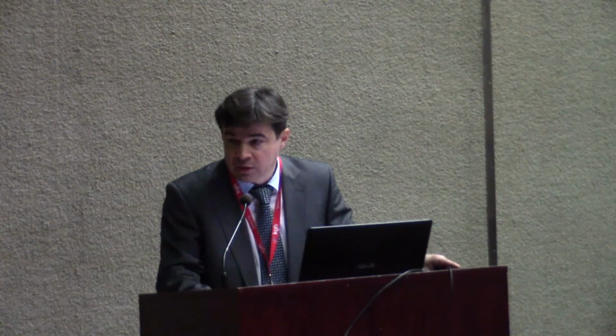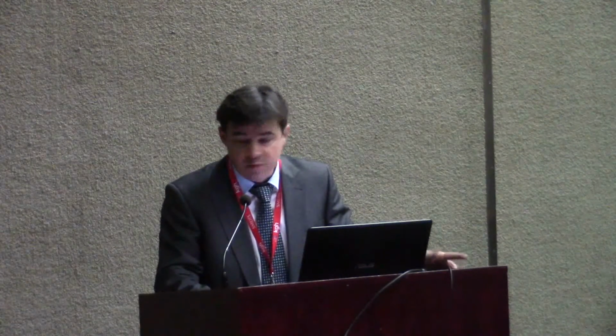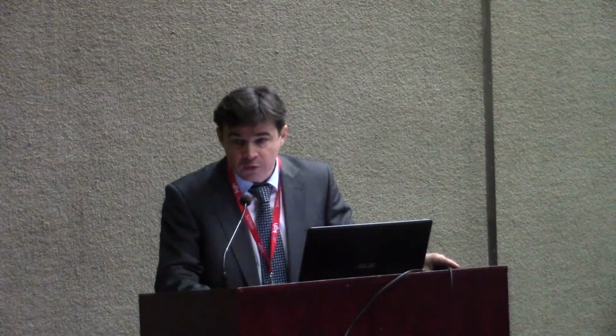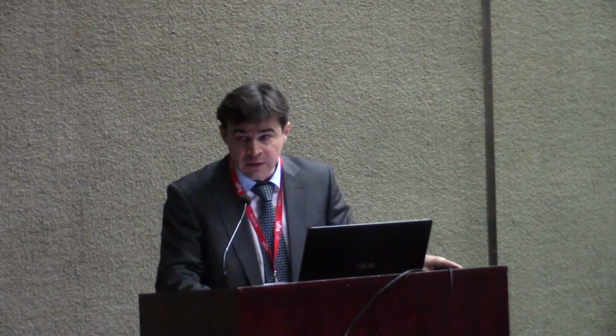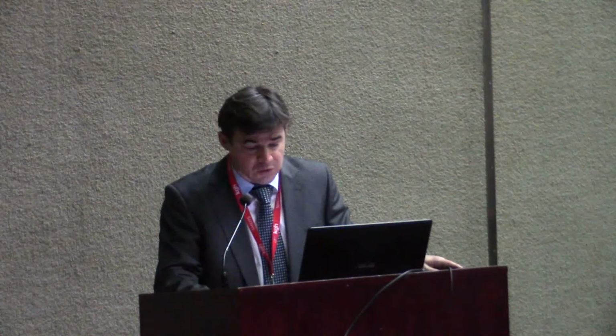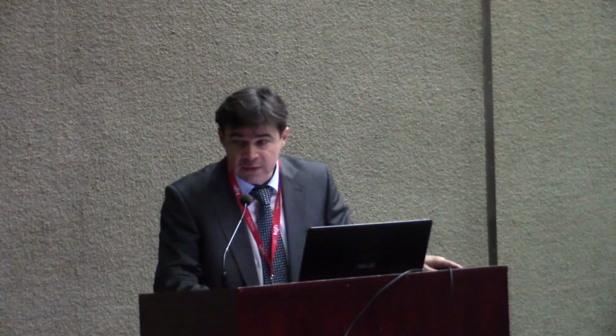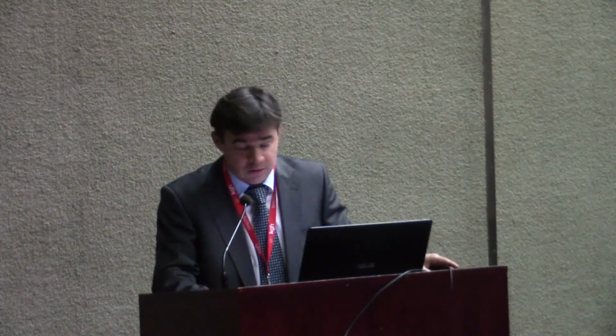What concerns air handling units, they are special design just because of great humidity, just because of chloramines. Modes of functioning are demonstrated on this slide. For example, upper left, air heating in water heater in night mode without moisture elimination. The second one, air drying from the space by means of cooling in recuperator and evaporator of heat pump. Third one, during the exploitation, it's obliged to supply fresh air according to norms. And another one, air drying on middle temperatures of outside air with or without heat pump.